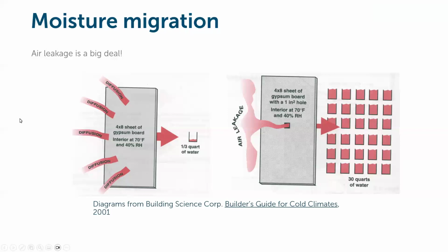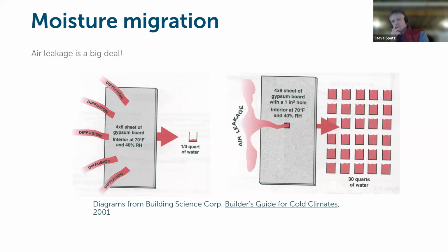Steve, but a question. Yep. And you might get to this with the ZIP-R system. How critical is the interior smart vapor barrier? Jeff has seen a lot of construction without the interior SVB. I think it's crucial that you have that, and you have some mechanism that allows for interior drying. I kind of see that interior vapor control layer as an insurance policy on the assembly behind it.